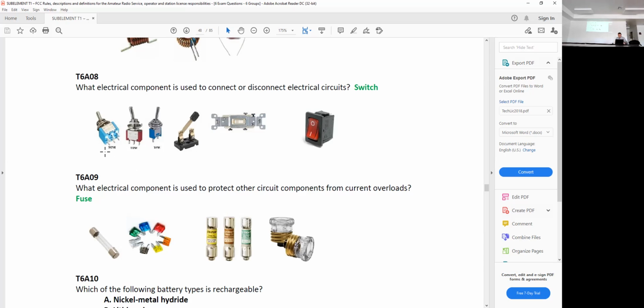And then the double pole double throw is the same as that, but you've got 2 of them in one package. So a total of 6 wires. And you might use that, say, in the same red light, green light example. Maybe you want to have red, green, and orange and white, but you always want 2 lights on. You always want the red and the yellow, or the green and the white.